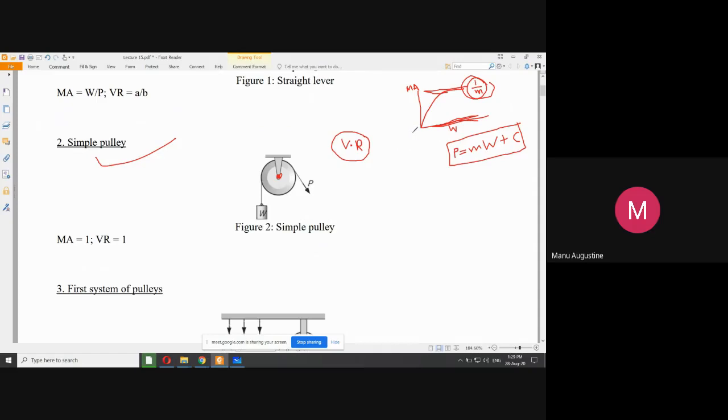So mechanical advantage, since it is not constant, we are not going to find any expression for it. It is useless to find a constant expression for mechanical advantage. All we are bothered about is somehow finding the value of velocity ratio, because once you find that expression, this is a constant quantity, and no matter whether friction is introduced or absent, whether load is increased or decreased, it does not matter. The velocity ratio of a machine is fixed and will never change. And you can remember an expression for velocity ratio. So, what is the velocity ratio of a simple pulley?